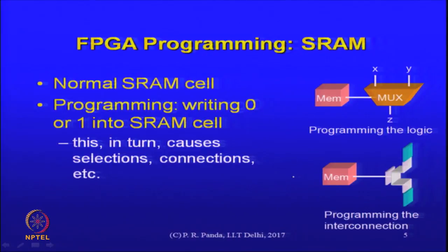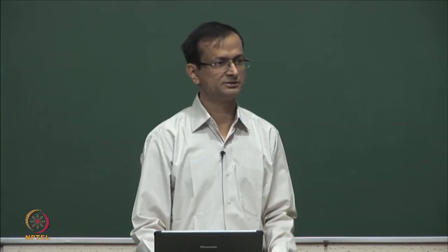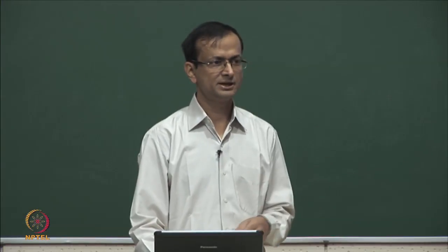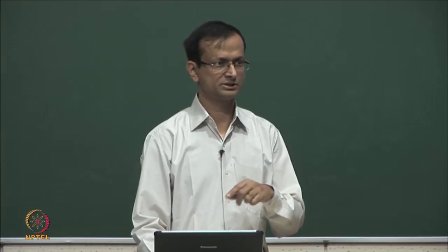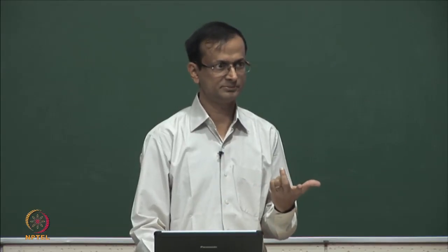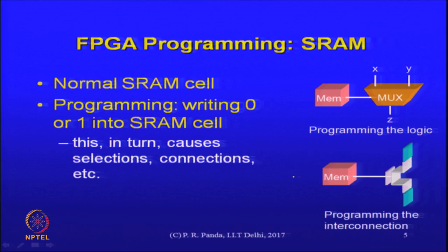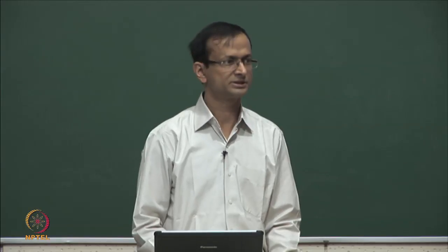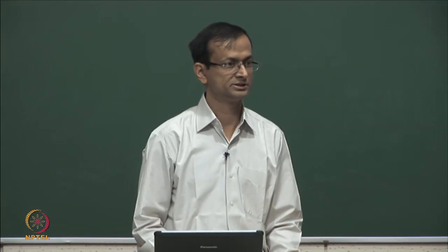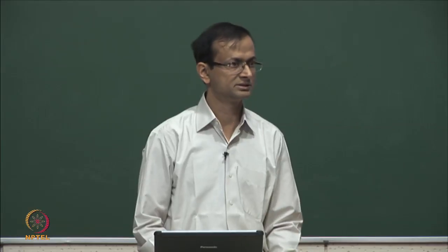People have tried what is called an anti-fuse element, where if you pass a current that is above a certain threshold, then that fuse breaks, and that distinguishes a short from an open, for example. That is inherently how programming is done on such a design. Such a system may or may not be reprogrammable multiple number of times. The implementation as a memory, of course, has a nice feature that tomorrow you change that value to 0 and the meaning is something very different.